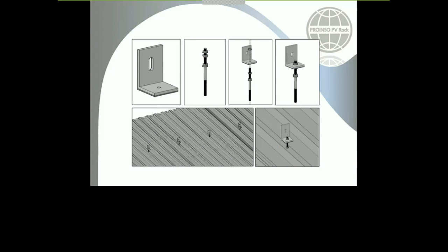Yes. If you give us the requirements that you have for a specific type of roof, to ensure that the solution is going to work properly, we will study it. For example, imagine that the kit has 20 centimeters of hanger bolt length, and your trapezoidal shape has a minimum of 10 centimeters, and then you need 5 extra centimeters for the fixing.